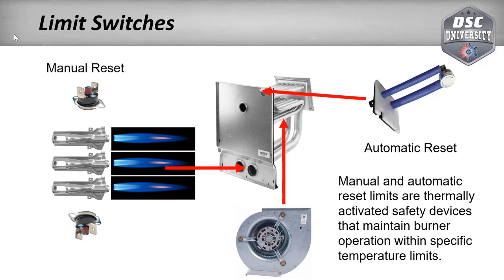What would happen is, when you went through the cycle, the burners would come on, and the flame goes into the heat exchanger. Let's say this panel back here had split open. So when the blower assembly comes on and it's blowing air across here, if that has split open, that air from the blower assembly would actually start going into the heat exchanger and push the flames back out to the front of the furnace in what we call a rollout. Right. And when that happens, usually it'll trip these limits out here. You don't see that very much because of the design of the heat exchangers now.